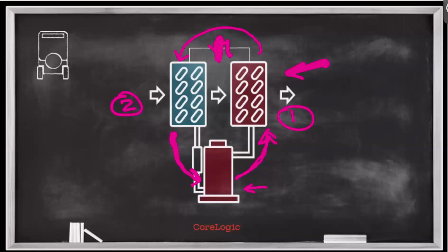Through compression, we're taking the amount of energy and making a much higher temperature. On the other side, we do the opposite. So imagine your hands out in front of you. You've got air the size of a basketball. Now expand your hands and expand that air to the size of a beach ball, right? Now you're taking the same heat and diluting it over a greater space. And what ends up happening is you end up with a high temperature on one side and a low temperature on the other side.